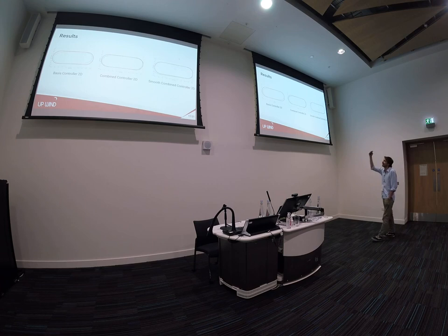And this is in a 2D plane. And the first one on the left is simply with a basis controller. And the other two are with a combined controller. So basically, you have to remember that the goal here is to follow the path more closely, okay? So, for example, in the middle, we have this MPC combined controller, right? And we're following the path much more closely. But the control isn't really smooth, okay? It's reactive. And so I added kind of a penalty for basically the rate of change of the control input. And well, that's the result.